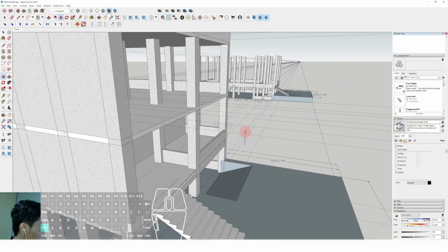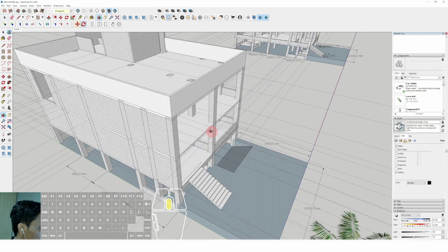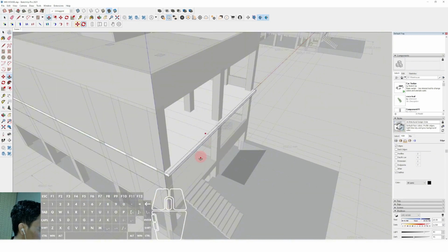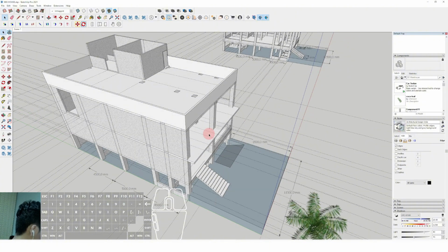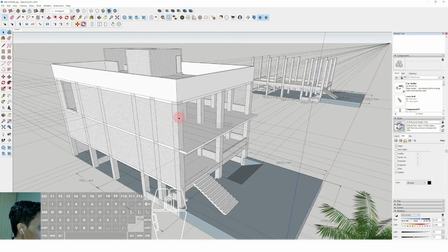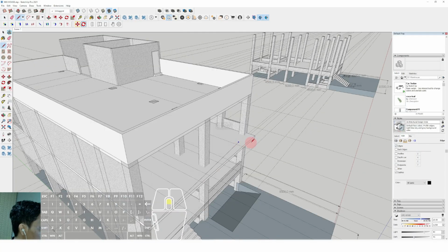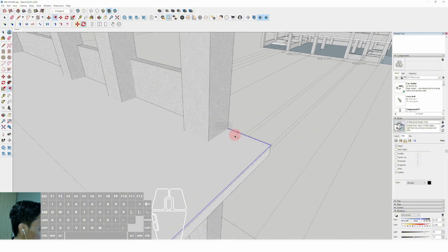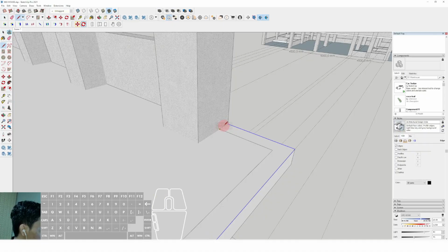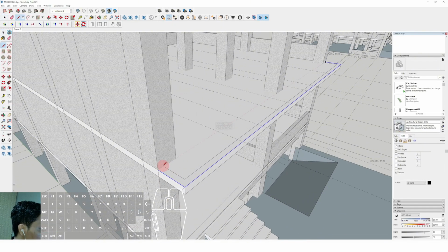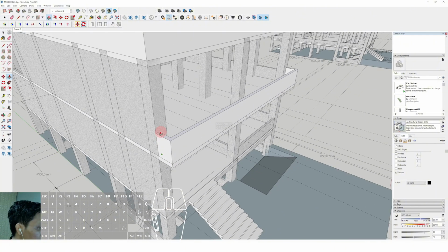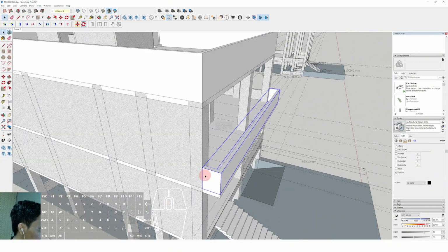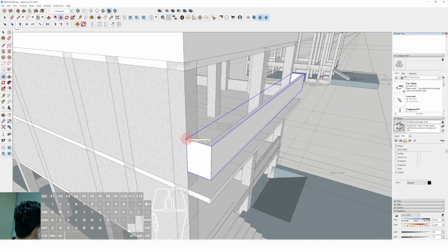So we can select move to the position. Okay, then we can give it a cantilever in here. Okay, and now we can make the extension of the wall. Okay, we can use the line over there. Can triple click, set it inside 150 millimeter, and also this one. We can type 1 meter, triple click, make group. Okay, we can select move. Okay, I will check about the rooftop size.